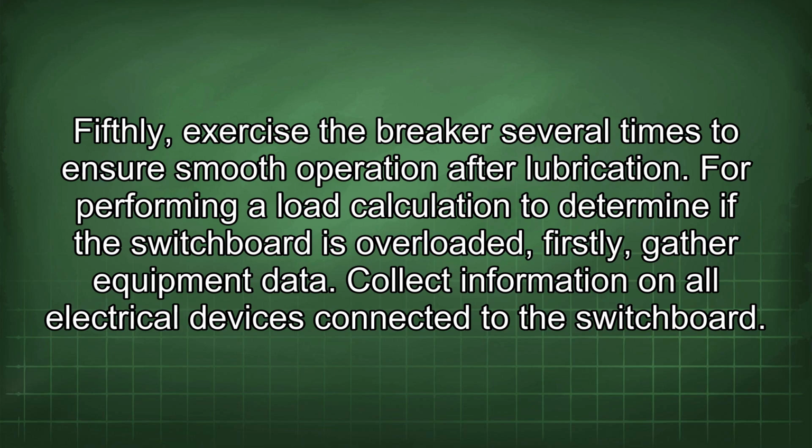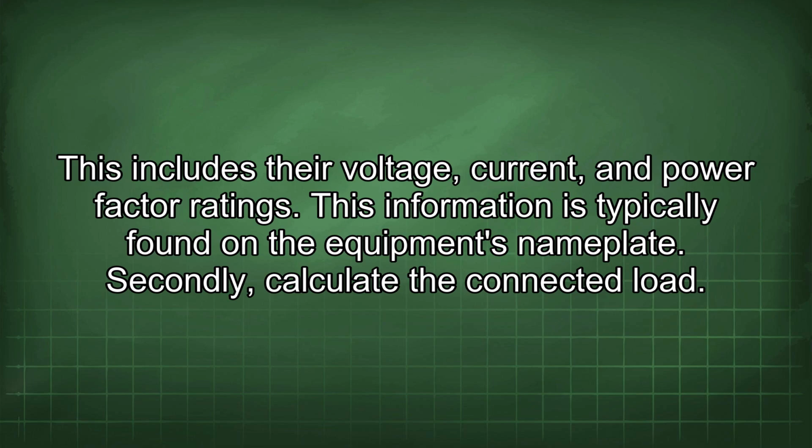For performing a load calculation to determine if the switchboard is overloaded, firstly, gather equipment data. Collect information on all electrical devices connected to the switchboard. This includes their voltage, current, and power factor ratings. This information is typically found on the equipment's nameplate.